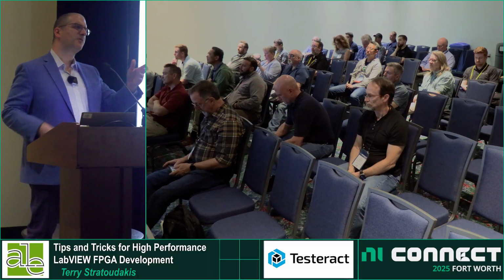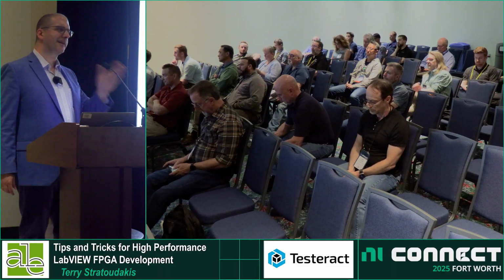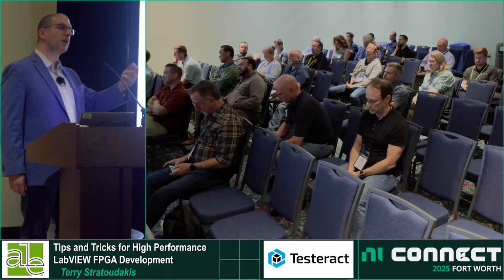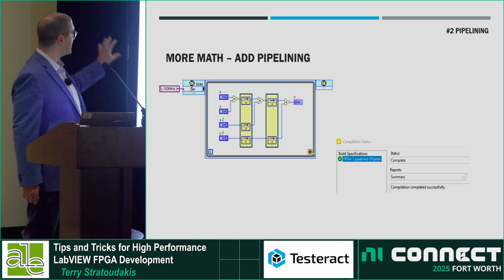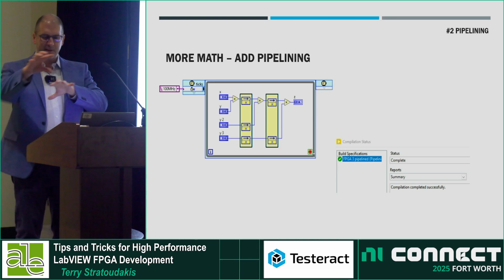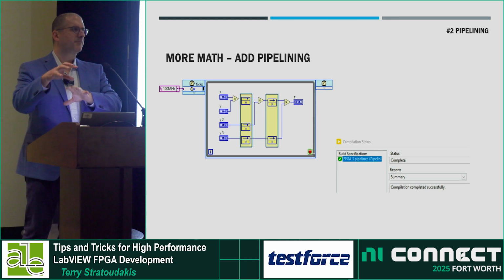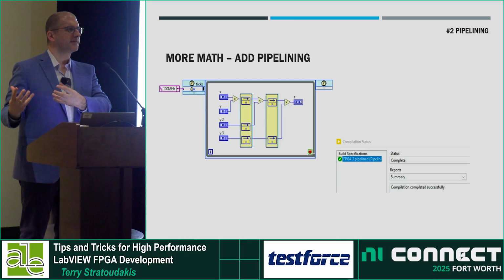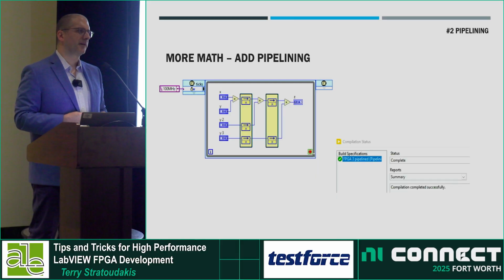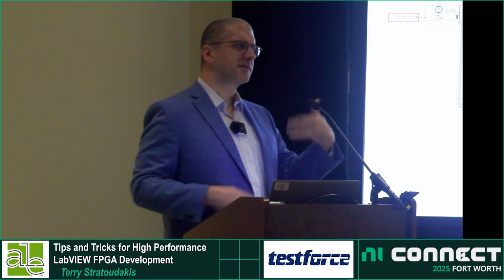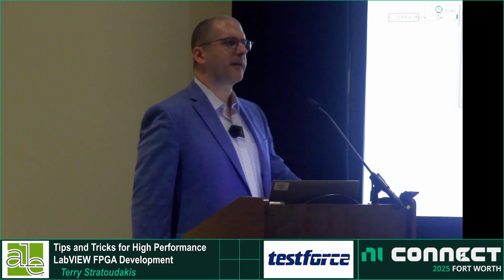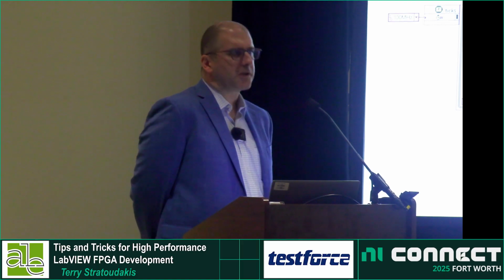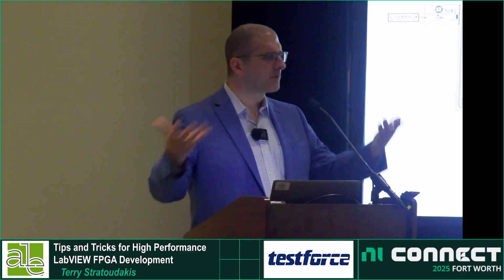Sometimes you may get a bit of a feel, but it's hard to really look at something and know, because other things also play into this. When it's placing and routing, it may hit congestion or other things, even though the design maybe wasn't that complex, that keep it from compiling. So a compile is a good checkpoint, like a test. We talk about test-driven development. It's one of the tests, I guess.